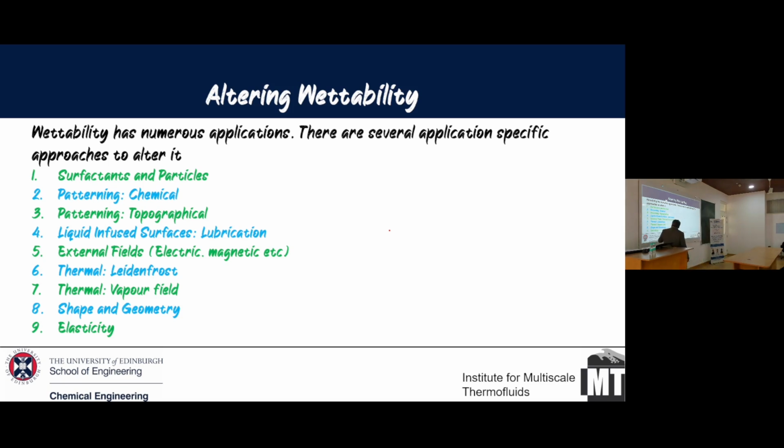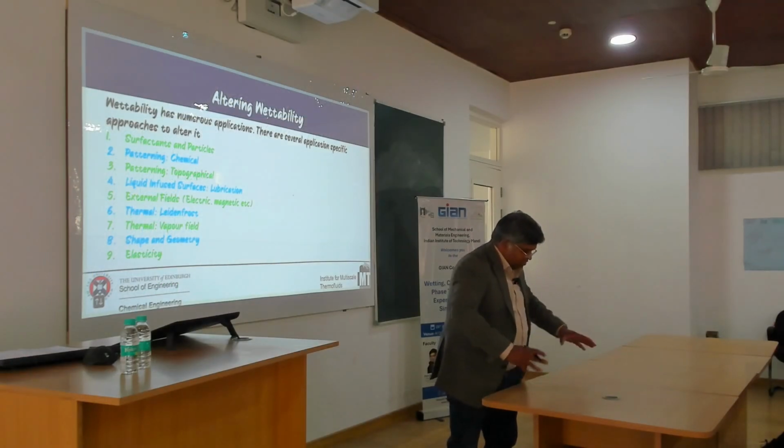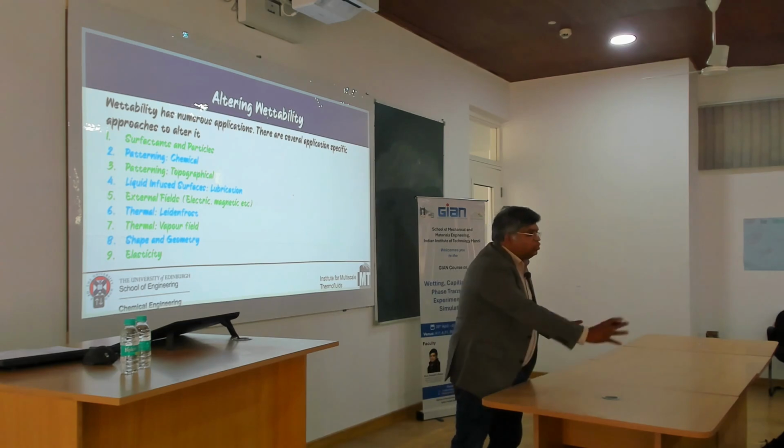Obviously, the other case which we are going to discuss further on is the use of heat. The moment you add heat, the contact angle changes. And this is one of the ongoing questions: how does contact angle change with temperature? It's an open-ended question, actually. So adding thermal, this is the surface feature where you have a Leidenfrost effect. You can have a vapor layer, and your droplet is sitting on that. The other one is vapor interaction. You have multiple droplets sitting all over the place, but the vapor composition is actually describing the motion of these droplets.